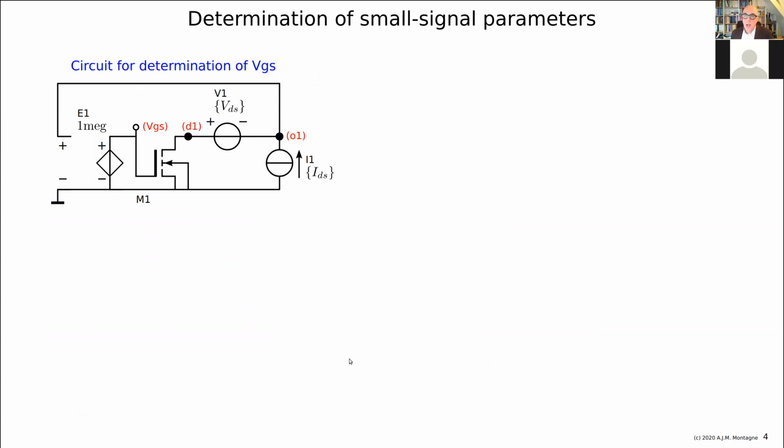So how is it done? Basically, we have a circuit, as I have discussed with you previously with the biasing. So here you say, I want to bias this transistor with this voltage and this current, and here it calculates with a large loop gain. You see, it calculates VDS and VGS, but the current in this model is 0, so we don't need that.